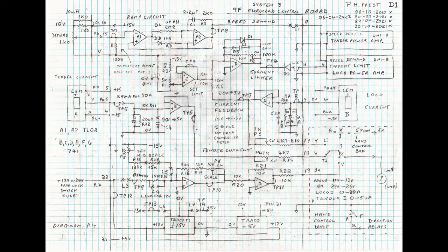The output of the op-amp feeds a scaled meter in a handheld controller, but it can also feed any other monitoring device. The diode minimises a reverse current indication to avoid damage to the handheld meter.